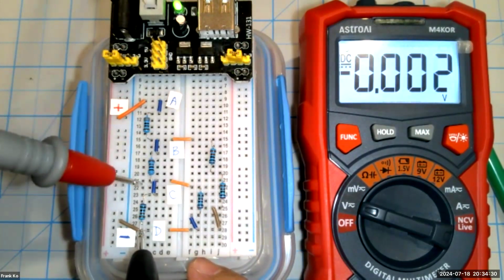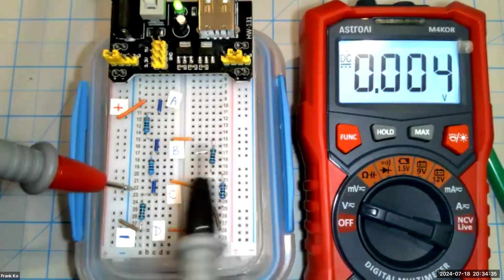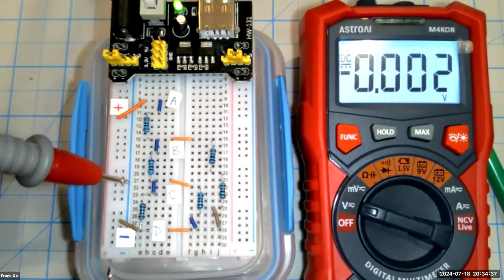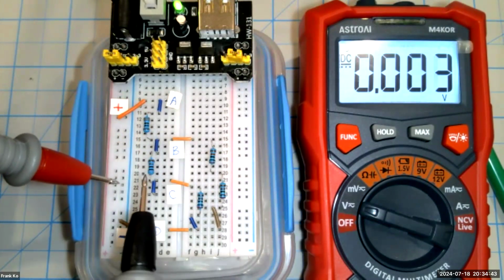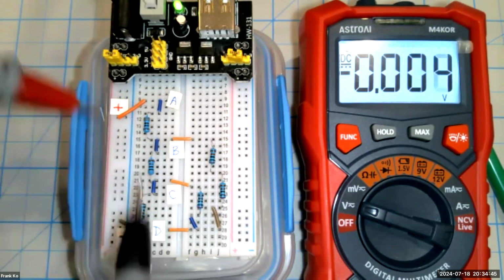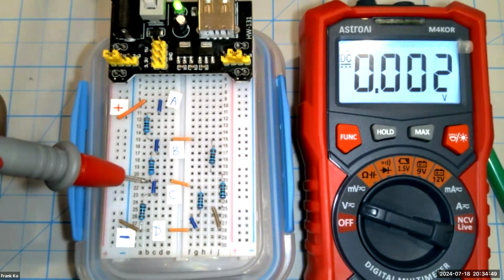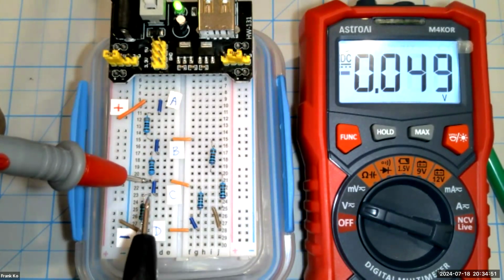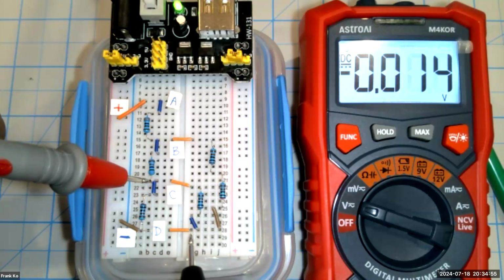Now at point C, we originally had 2 volts, but once we added the loads, it was way less than 2 volts, to something, 1 point something. Now with the appropriate new R1 and the appropriate new R2 changing up the voltage divider sum, we still are able to maintain 2 volts at point C to supply the needs of the R4 resistor. Let's see if we get it.